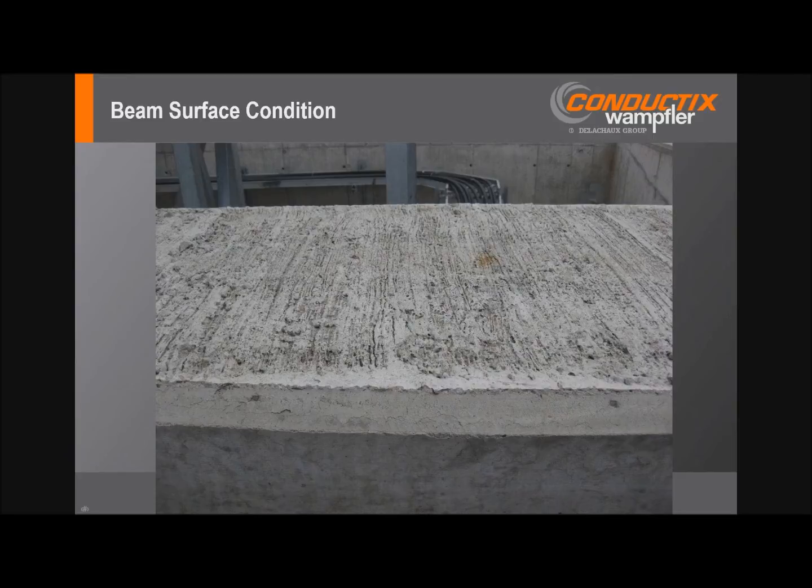When electrical erosion occurs repeatedly in a certain section, it creates a cheese grater effect, and this hard, sharp contact surface can then severely damage shoe life. If not detected in time, the combination of a severely worn shoe and a pitted conductor surface leads to a downward spiral of condition and requires essentially replacement of the conductors.